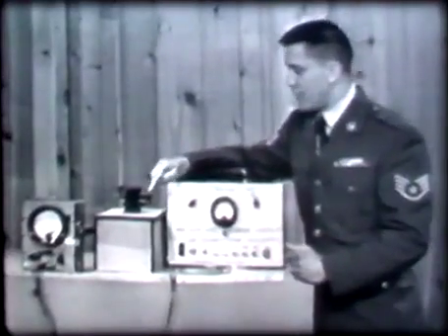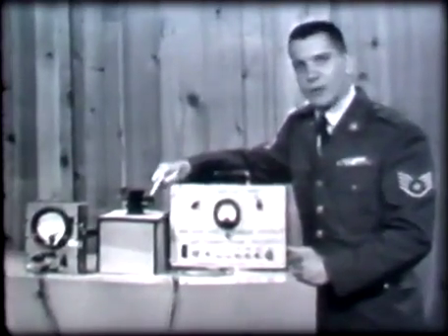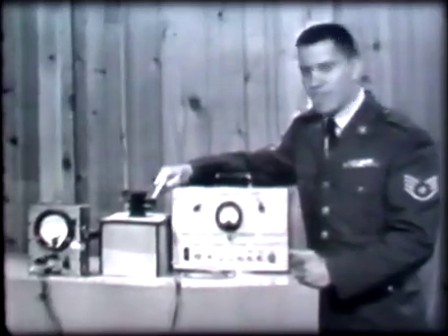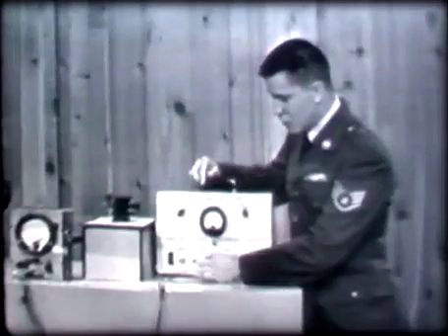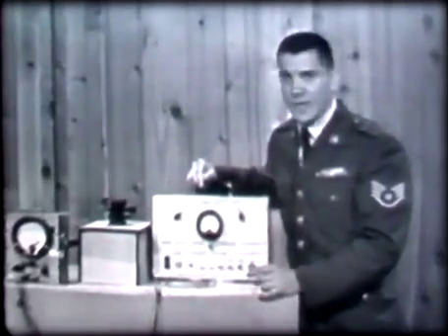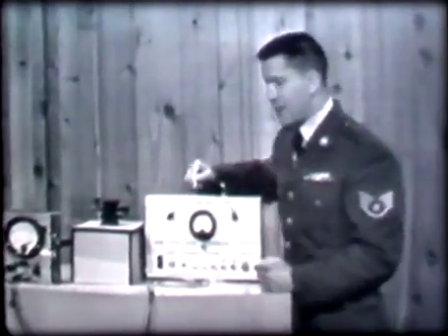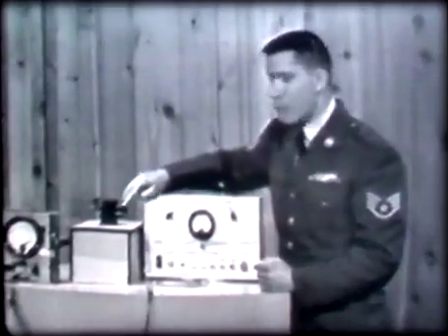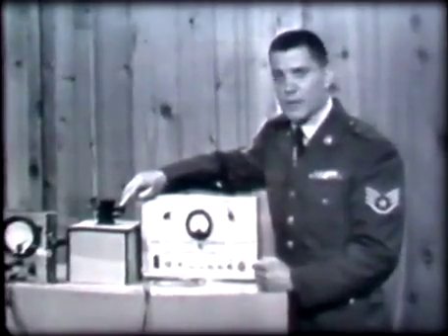The demonstration will be using the bottom winding here as the primary. Now, here I have a power supply, and from these two terminals on the power supply, we can obtain 6.3 volts AC. I'm going to apply that 6.3 volts to the primary of this transformer. Then we'll use our PSM6 and measure the voltage available at the secondary.